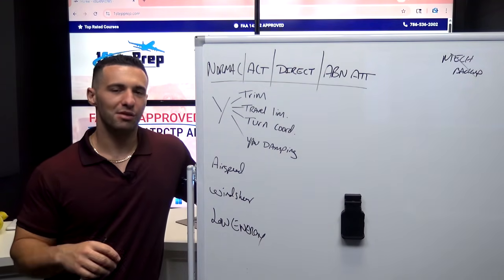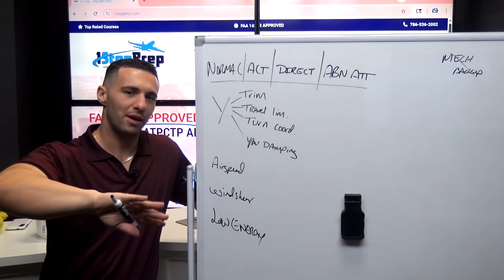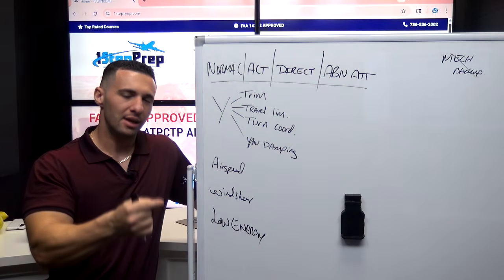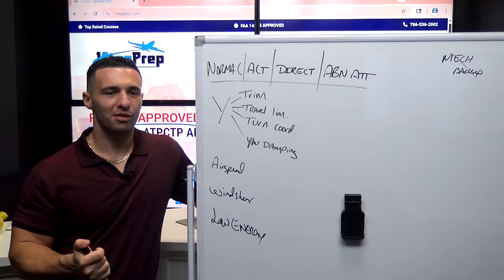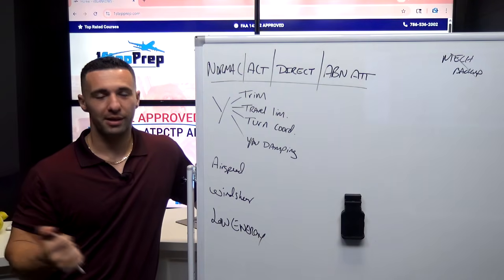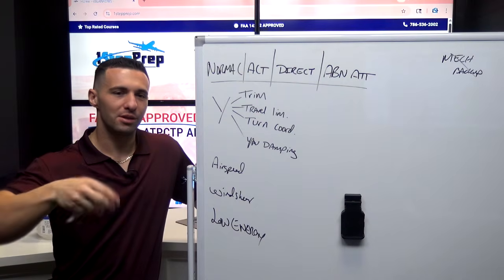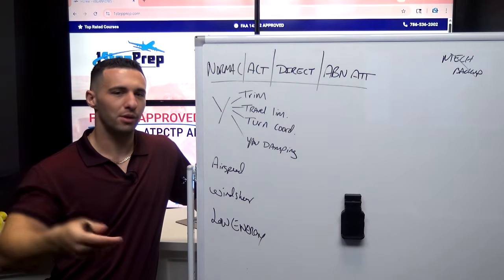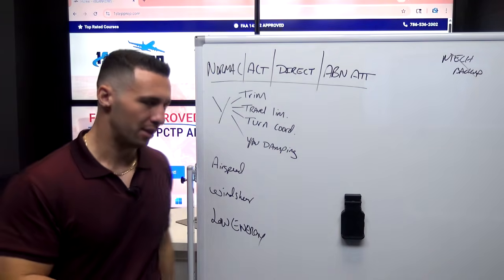Not frequently, but in the circling approach you could potentially get the low energy warning because you're banking close to the ground. You're very slow. The VLS is creeping up on you. And another thing that could happen in circling approaches is alpha floor activation. That's usually why they recommend having selected speed until your circling maneuver is complete, and then when you're on the final approach course, managing it up so that you prevent that from happening.